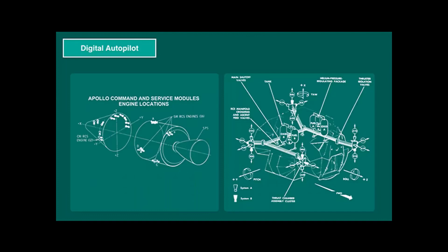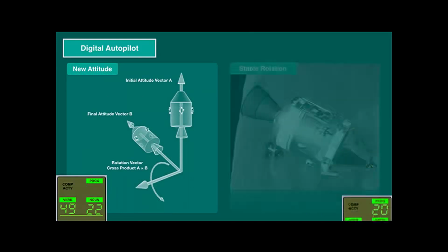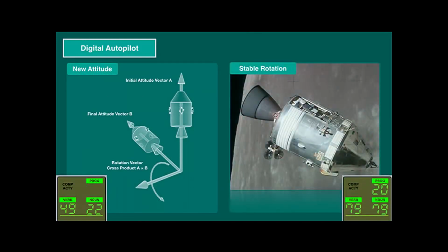It has some simple algorithms for center of gravity and weight distribution as well, which are taken into account in calculating thruster maneuvers. It can do more than that though. Give it a new attitude and it will calculate the most efficient transfer vector to reach the new attitude. In certain flight modes, it might be required to have a stable rotation, be it for temperature control, monitoring of the landing site, or other reasons. The autopilot supports stable, constant rolling, which can be directly activated.